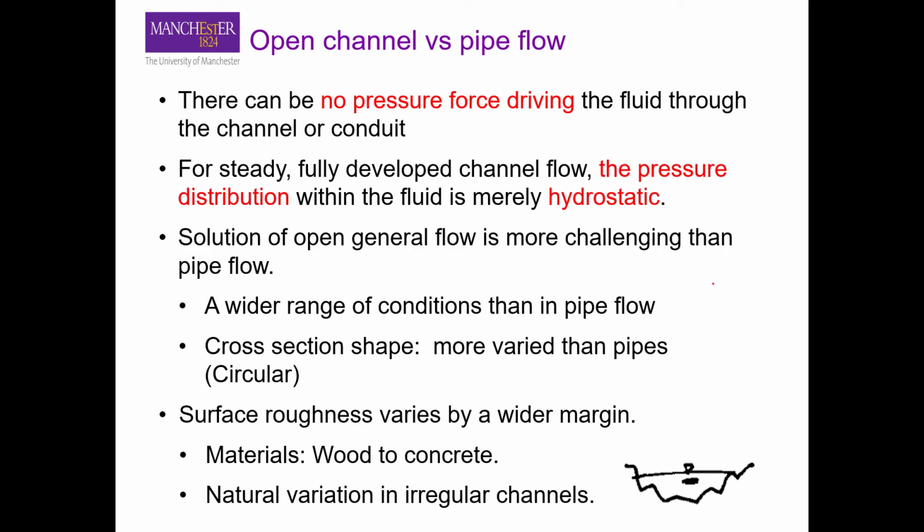And for the course of this unit, we have been mostly talking about flows in closed channels that are normally known as pipe flows. So here I just want to make a comparison between pipe flow and open channel flows, and how they are similar but at the same time different. One biggest difference between an open channel and pipe flow is that for open channels we have a free surface, while for pipe flows we don't have a free surface. Okay, it means that in a pipe there is no free surface, the pipe is filled with the fluid.